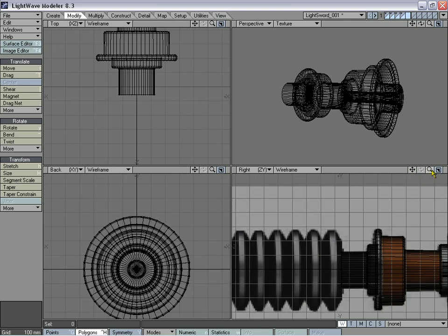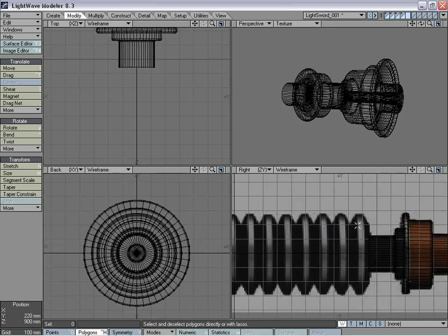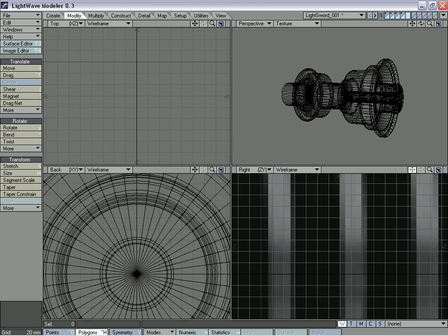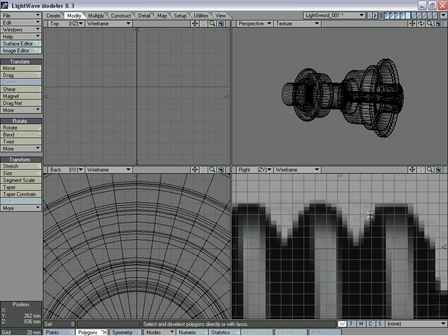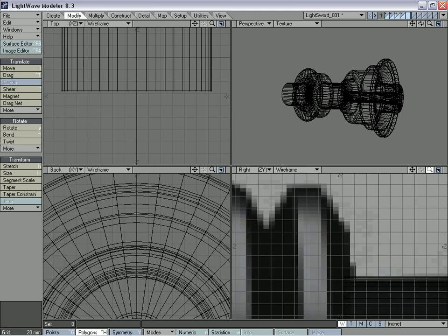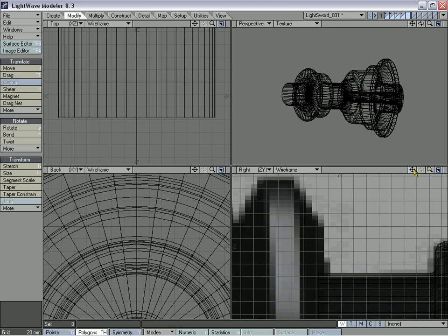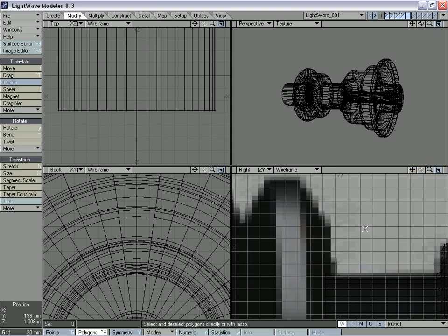And we're going to do this all as one polygon and one lathe. We could do it as each individual ring, copying and pasting them over, but we want all of this to be connected in here, so there's a nice smooth, and we'll pick up a highlight along the edges, and we don't want a sharp crease by having two cloned items or copied and pasted items right next to each other, interlocking. Alright, so we're going to Shift plus again to create our points.